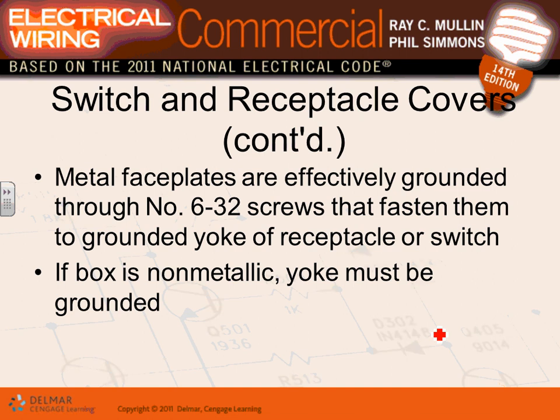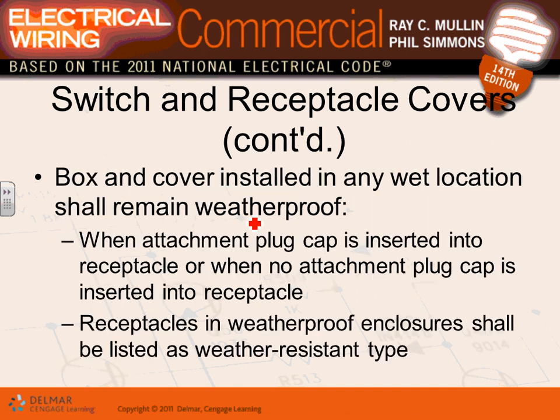If you use the plates, guys, you have 2 screws, and these screws you attach to the yoke, and by doing this, one screw, if it's a receptacle, by attaching it to the yoke, you have just grounded that receptacle. If you have a non-metallic yoke, you have to ground it directly.